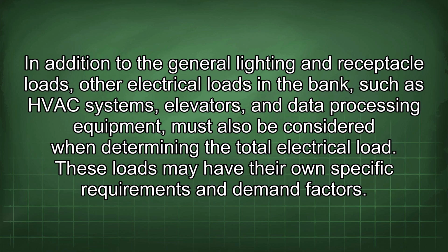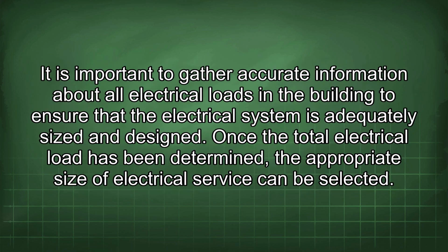In addition to the general lighting and receptacle loads, other electrical loads in the bank, such as HVAC systems, elevators, and data processing equipment, must also be considered when determining the total electrical load. These loads may have their own specific requirements and demand factors. It is important to gather accurate information about all electrical loads in the building to ensure that the electrical system is adequately sized and designed.